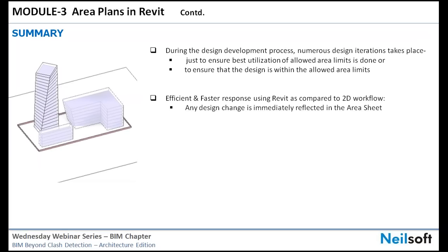Any design change you make is immediately reflected in the area sheet. The area schedule is automatically updated. You just need to update the area boundaries. And the beauty is that you can also lock the boundary lines with certain elements in the design.